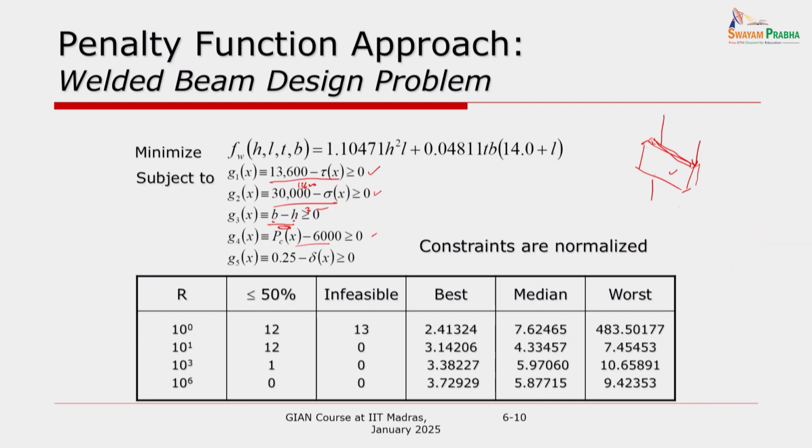I could use the GA that I've talked about so far, and I ran it 50 times. I think this was coded in binary strings, because I did this way back. I think this was my first paper actually. It was in 88. This was my class project for the GA class that I took, and there was an opportunity for a conference as a student paper, so I submitted this one. It's a first application of GA to this kind of structural engineering problem. And at that time we didn't have sophisticated constraint handling methods, so we were using the penalty method. I ran 50 times.